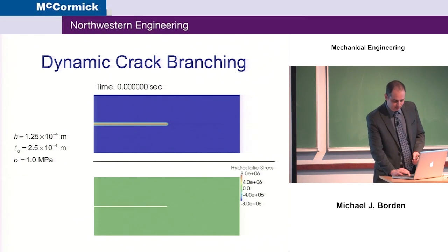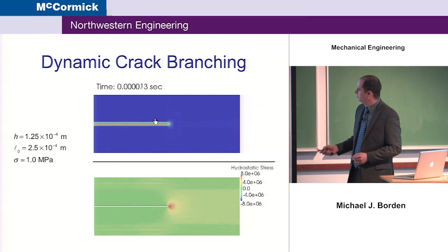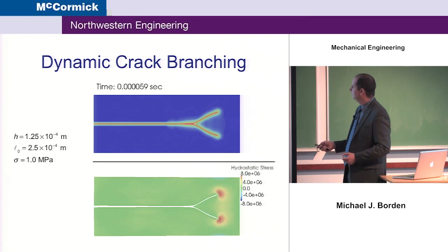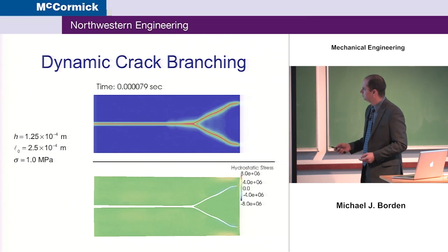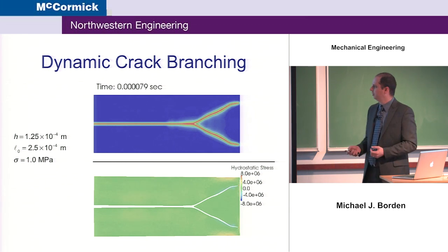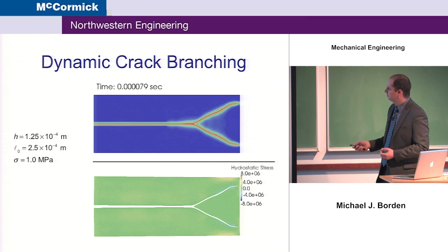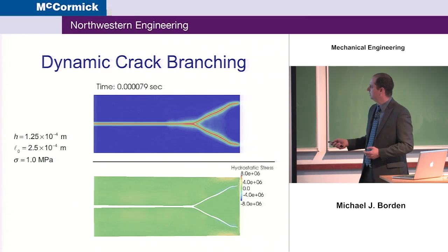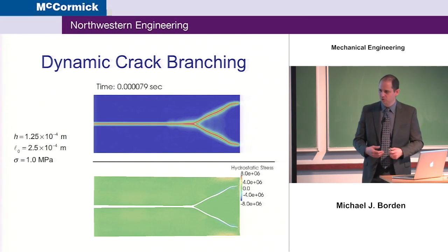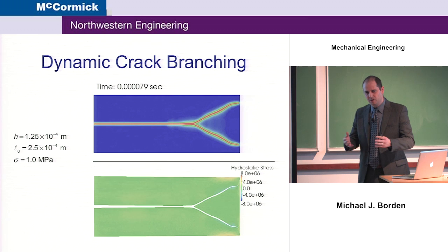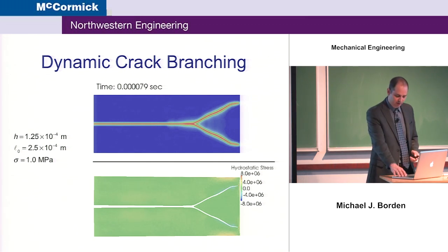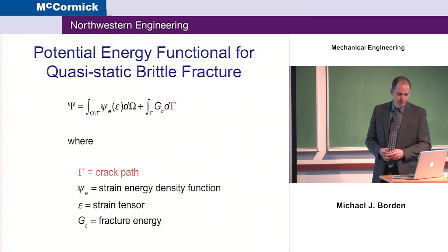And so we'll just show it here. Here you can see that the crack begins to propagate. We get some branching where there's a buildup of energy. It needs to release more energy. We get a crack branching. And this happens completely described. This branching behavior, the nucleation, the propagation behavior is completely described by the model. There's no indication in there that says this is when the model needs to branch, or this is the direction the crack needs to go.